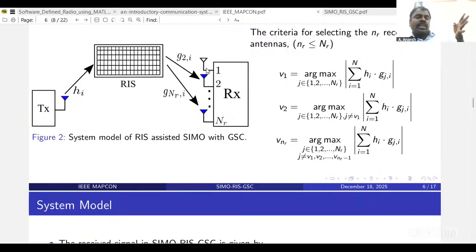So now from all of this, what can we infer? We can infer that the first antenna is giving 2, the second antenna is giving 4, the third one is giving 0.5, and the fourth one is giving 0.25. So which channel gain is more? The second channel gain is more. This means channel gain is nothing but the magnitude of H1, magnitude of H2, magnitude of H3, magnitude of H4, and so on. Channel fading coefficients mean H1, H2, H3, H4. All of those complex coefficients are called channel fading coefficients. The magnitude of that is called channel gain.